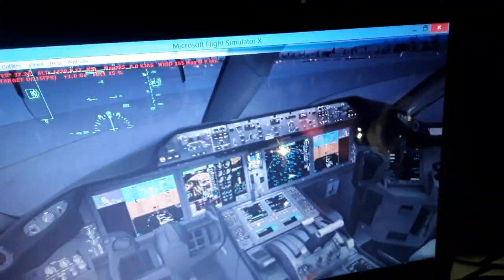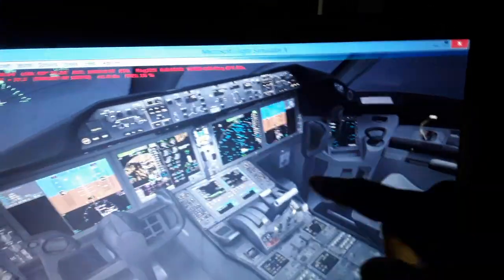So we have a higher intake of air from the front fans of the engines for compression and fuel mixture. Also, the temperature becomes freezing, like -30, -40, -50, -60 degrees Celsius below zero. So we need a different fuel mixture every second. This is adjusted automatically using the FADEC. Also, as we descend back to the airport from the cruise level, it's a good thing to have the FADEC to control everything in your engines.